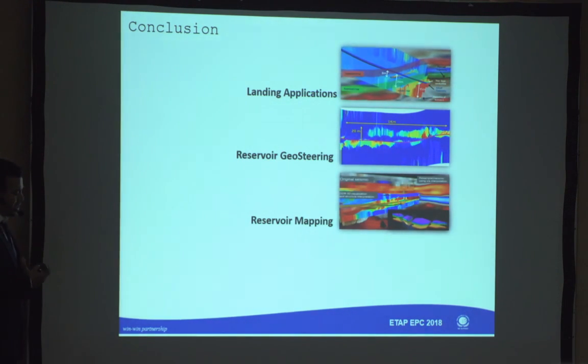If we think about the ultra-deep electromagnetic signal, how it moves into the formation, how we can capture it, even how we can change the algorithm to capture the ellipsoid of the electromagnetic signal. So we use this technology in the landing application to place the well in the right spot without losing a lot of budget.